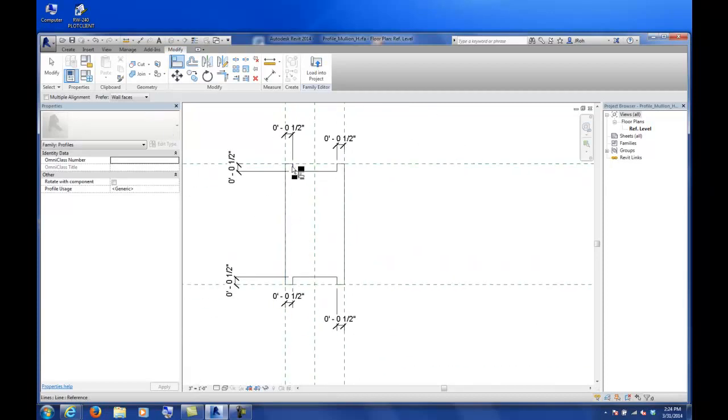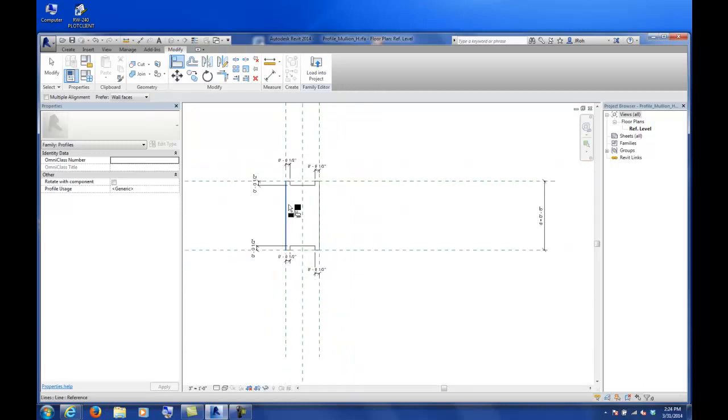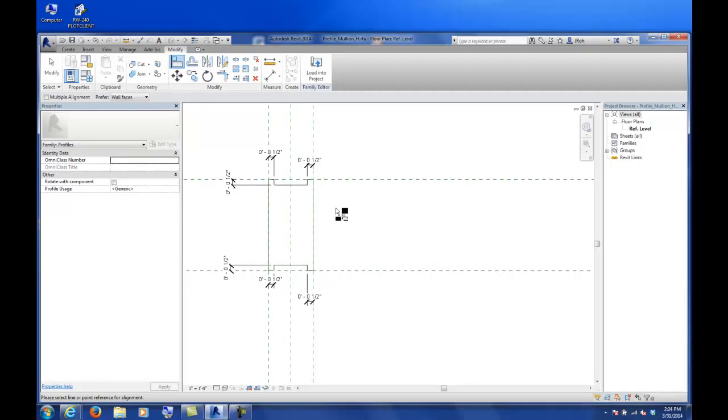It's basically just some drafting, but again, I'm making it parametric by these reference planes. And the reason to make this and understand this profile family and how to make things parametric is really key, because in order to have your railings and also mullions and all these other tools that we're about to use reference these components, in order to size them, you have to make your component parametric. Well, you don't have to, but it makes things a little bit easier. So again, if you can't get it to be fully parametric, at least get it to that shape.